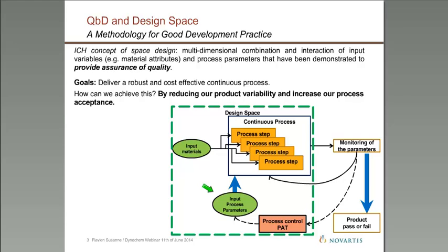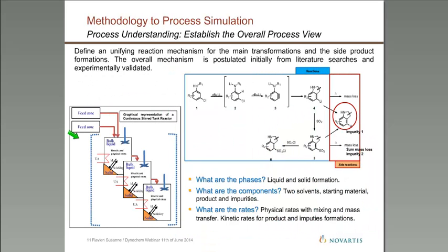And these can be monitored, obviously, through the instrumentation, and we have to make some adjustment on the process, or we can directly go for a strategy of pass and fail. So we have the time of addition, we are stirring, or mixing anyway overall. So we have the mixing time, we have the mass transfer, we have the heat transfer, we have the kLa. So all these physical rates need to be integrated within the overall simulation to have a better understanding of how it works.